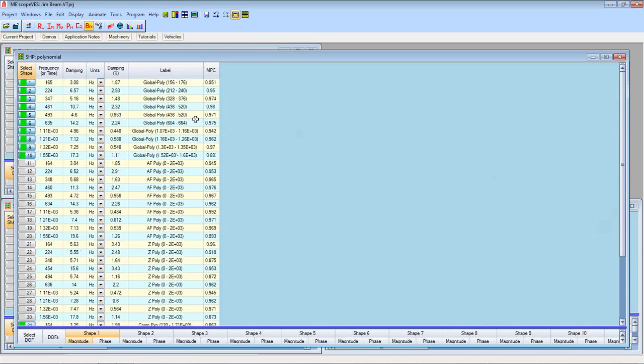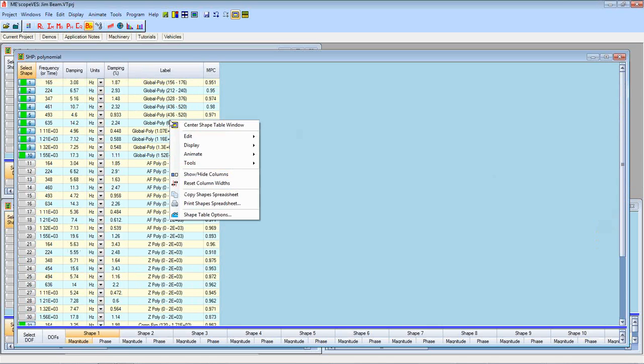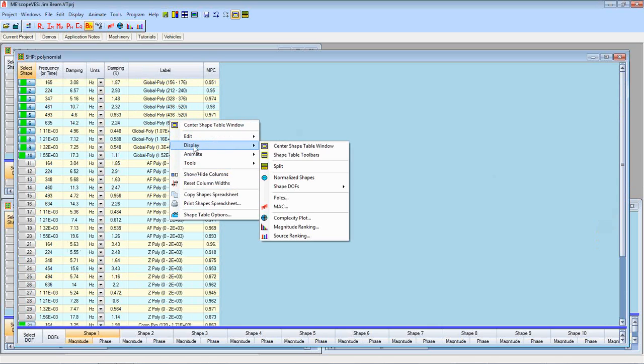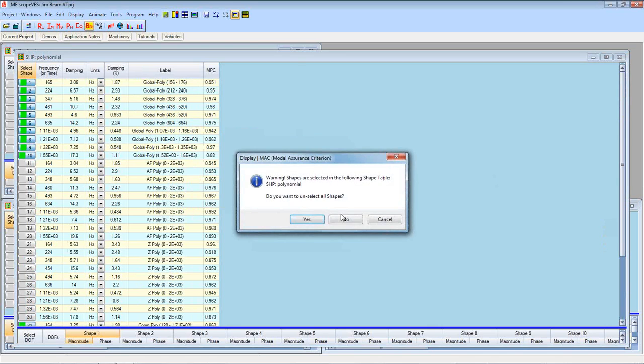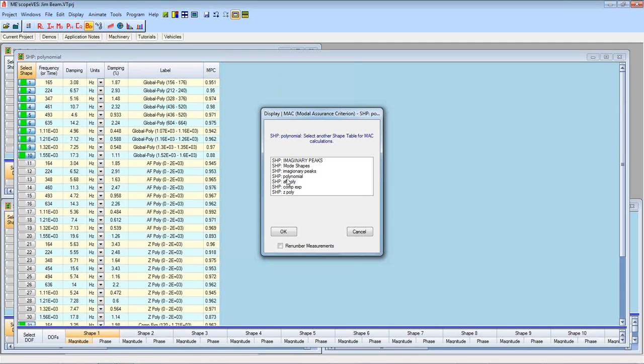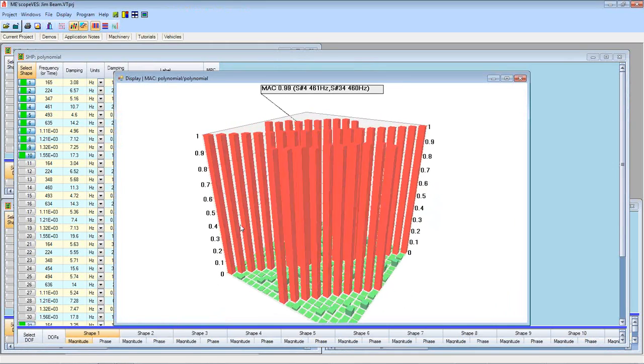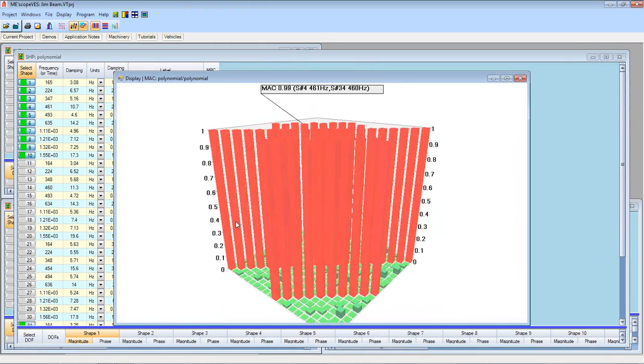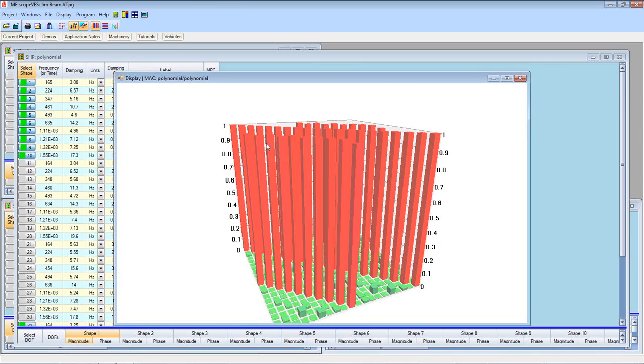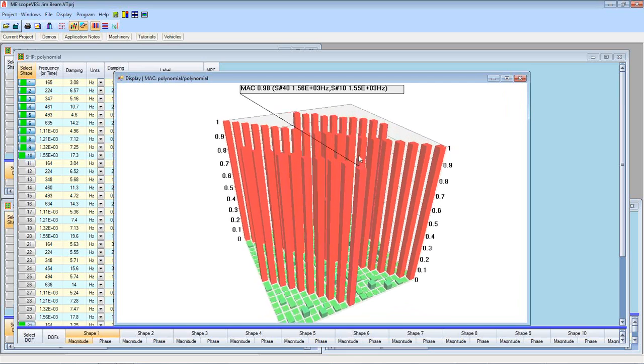And I'll compare their mode shape. So this is the polynomial versus the complex exponential. MAC value, polynomial. There again, you can see the MAC values are very good. I think the worst case here is this one, 98% at the 1500 hertz mode.